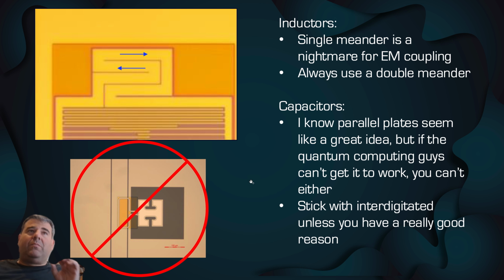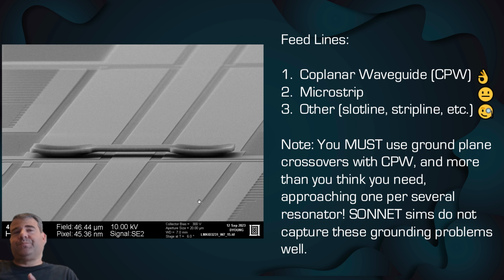The loss is still much higher than the crystalline dielectrics you get on these interdigitated resonators. However, most people don't have access to that amorphous silicon process, and if you're starting from scratch, you really don't want to go with these capacitors unless you know what you're doing. And I still think you may see extra TLS noise from the deposited dielectrics. So avoid those if you can.